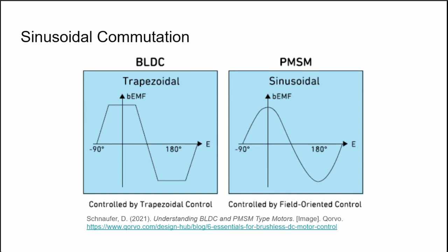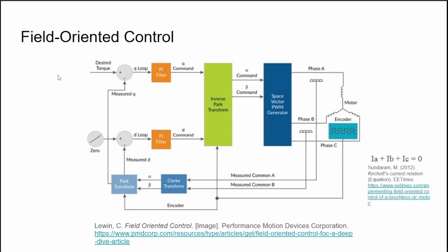However, there is one issue with this. At high speed, there will be some lag in the desired current, which results in inefficiency. Additionally, current may not be in phase with voltage, and back EMFs may be generated as the motor spins. That is to say, a simple lookup table may not be enough. So this is where field-oriented control comes into play. Field-oriented controls, or FOCs, adds a PI controller and a bunch of spooky math, which we'll get into, and this will get it ahead of the curve.